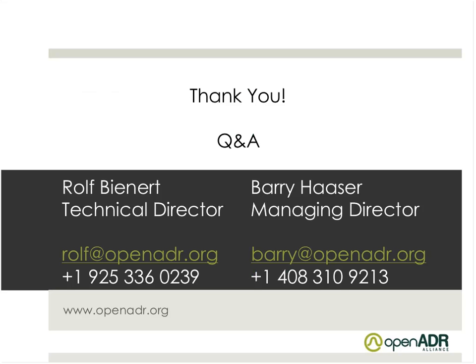So in order for OpenADR to operate, it needs an internet connection. If you had an IP-based AMI solution, in theory, you could send OpenADR signals through that AMI infrastructure. What we're starting to see is the deployment of a parallel network where AMI is used for what AMI is good at, which is remote meter reads, outage detection, power quality measurements, et cetera, and OpenADR is used as a way to get fast demand response messages to a customer.